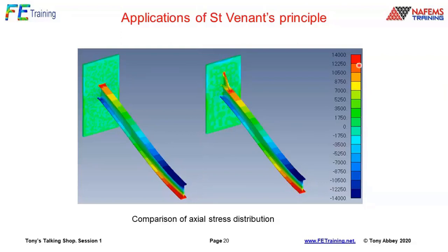Here are the stress and displacement results for the two. I've clipped the same stress levels, which kind of characterize the bending at the center here. We've got peak bending here, then reversal of bending as we come down to the root, and we also have a stress concentration at the toe there. So that's basically the idea. So I'm going to drill down a little bit, to see the difference between these two.